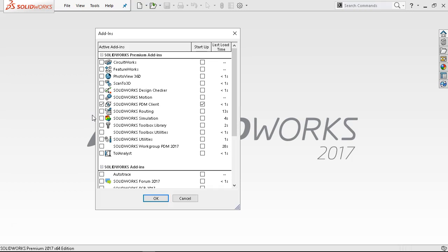At the base level, you have Simulation Express, which will work on a part in basic and professional. It does not do assemblies. In the premium level, you will be able to do a static simulation on parts, multi-body parts, and assemblies. And at the simulation premium and professional levels, it goes into frequency, buckling, drop tests. There's 8 or 9 tests that you can do within the simulation to set those up.